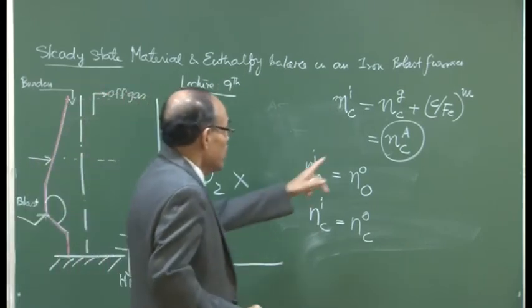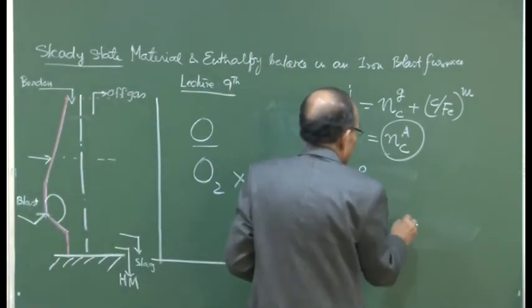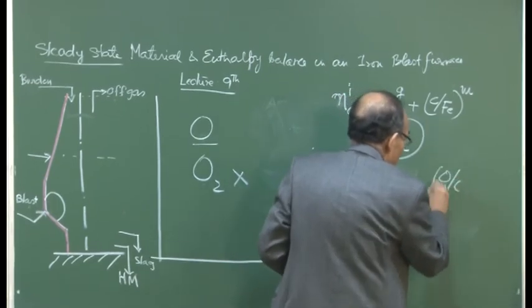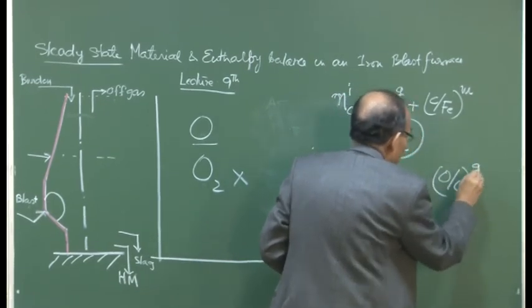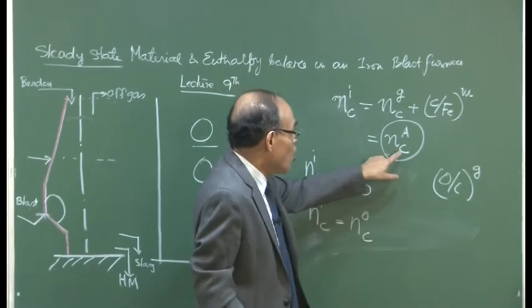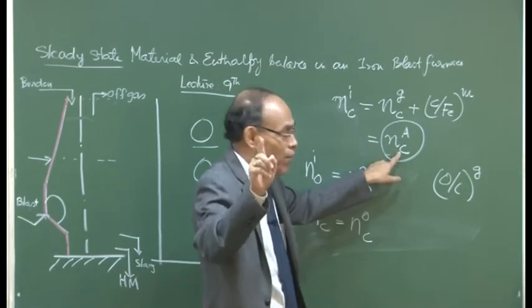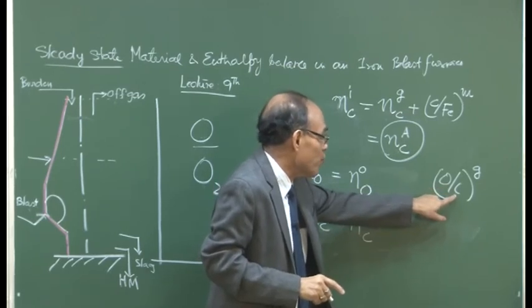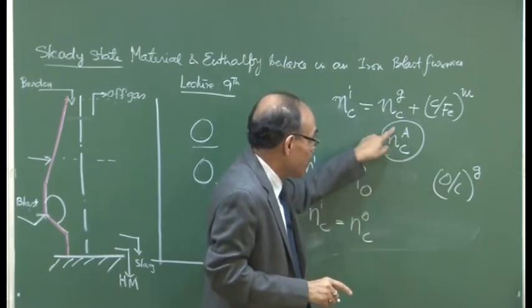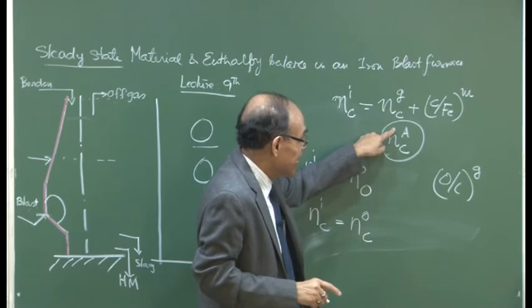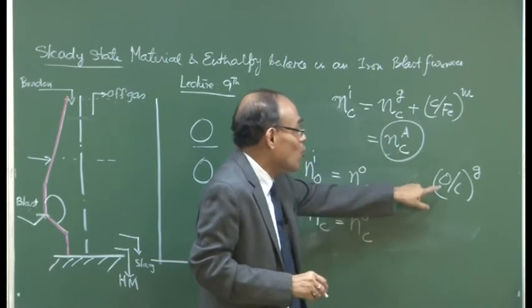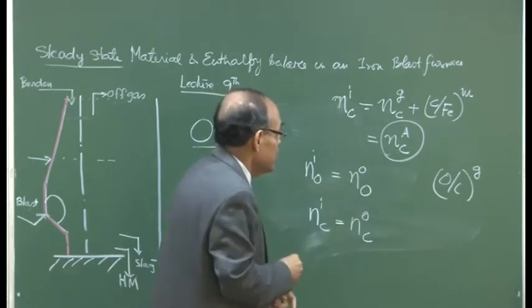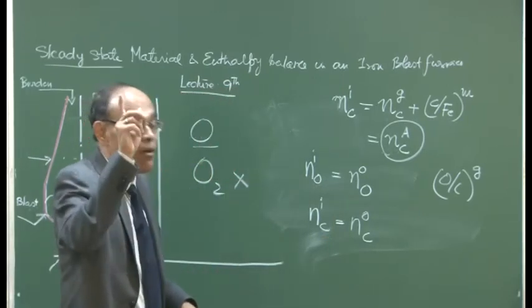Now, the gas phase has O by C of the gas. If you multiply this, what do you get? This is moles of carbon per mole of Fe, and this is moles of oxygen per mole of carbon. The moles of carbon cancel out, so this is the oxygen in the top gas per mole of Fe.